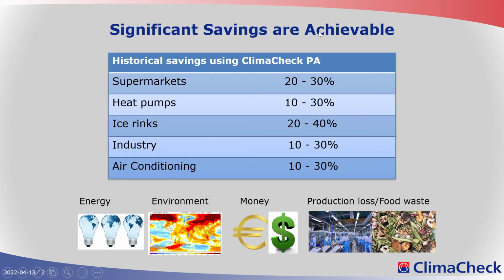So, of course, the purpose of doing these analyses has two different aspects. One is the energy saving. I mean, we are wasting a tremendous amount of energy in our industry today because the systems are not optimized. They don't run as they're intended to. So there are faults in the system, and there is a lack of commissioning, and there are different components in the systems not matching each other as they should.